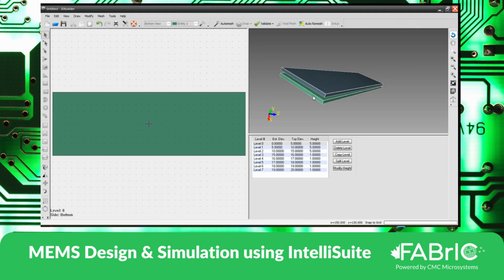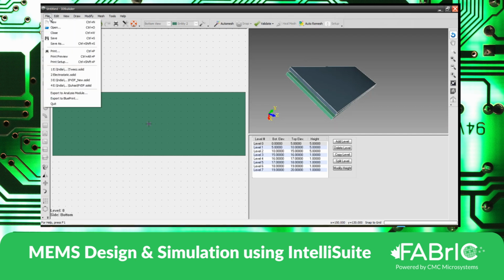Okay. Instead, if the two entities are different, then the software differentiates that it's two different entities and I can define two different voltage conditions. Okay. Same goes with the material properties as well. Common entities are with same material properties. So now please remember that I'm trying to save the file which I've created as just a geometry. It has no link with material properties or any loads, boundaries, nothing. I have just created a geometry as it is.